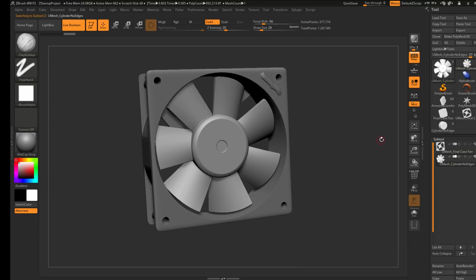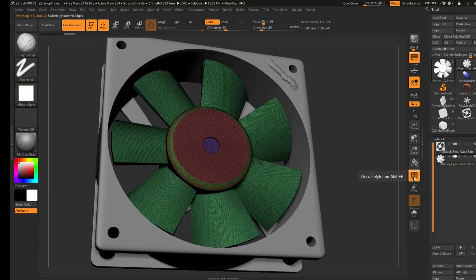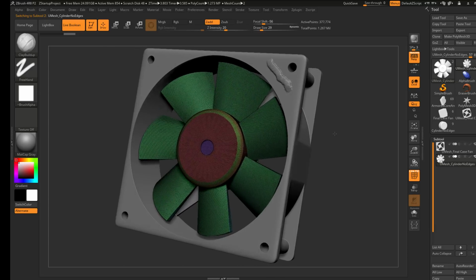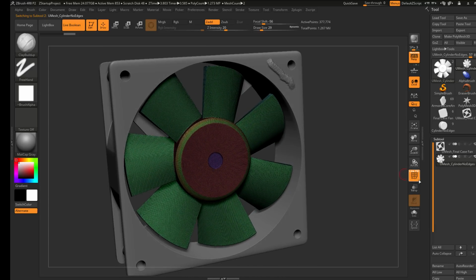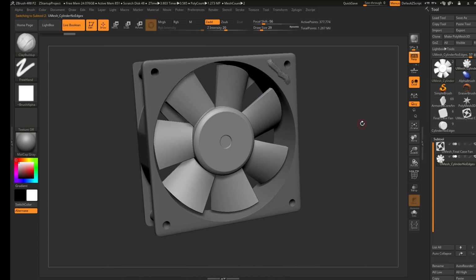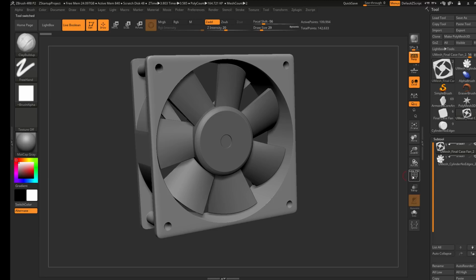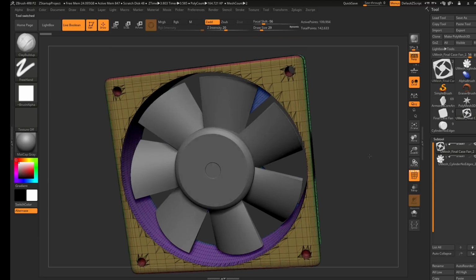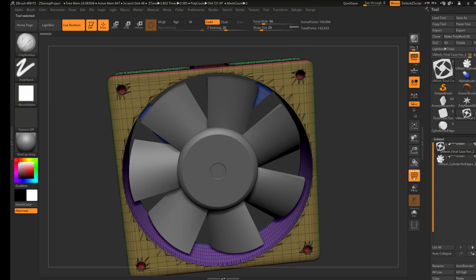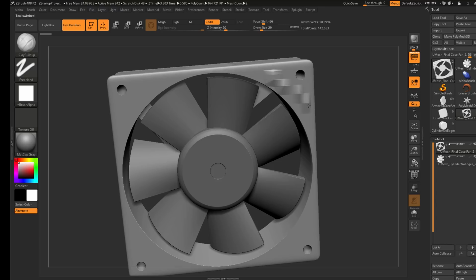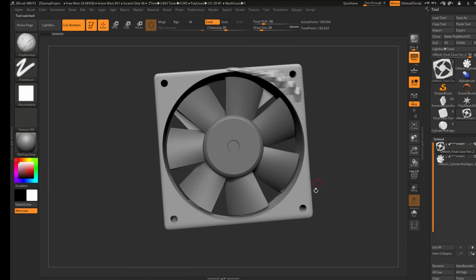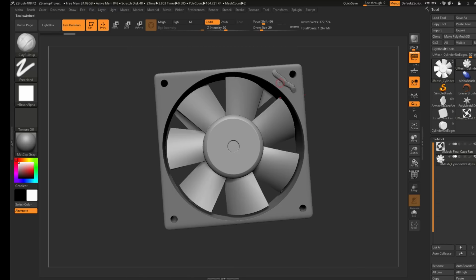And it's processed both of the start groups there with that DynaMesh option. So it's gone through and processed with the Boolean and then automatically turned them into a DynaMesh. So this is the DynaMeshed version here. And then if I go to the other version, which was processed without DynaMesh, you can see that this is the result. So this gave me the Make Boolean Mesh result. But you can see, since it is not a DynaMesh, if I try to sculpt on the surface now, it's not going to give me that same result that I had if I applied the DynaMesh after processing.